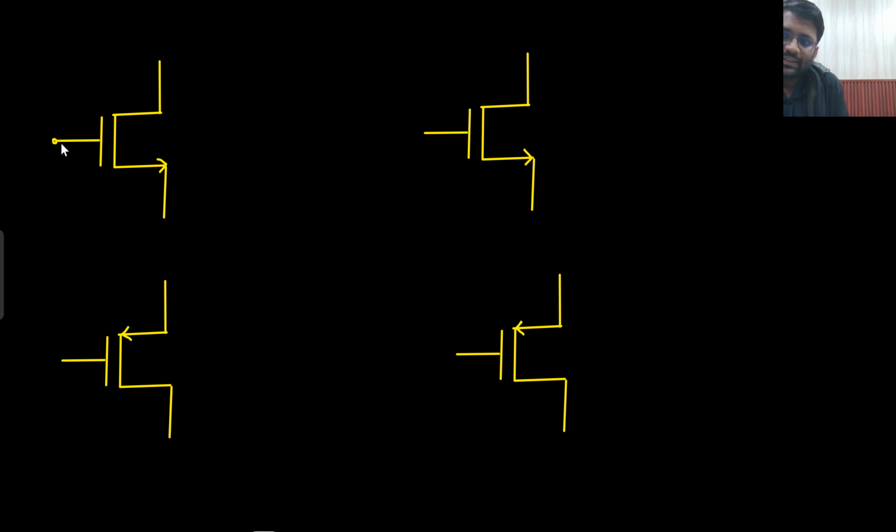Okay, now let's just say I say this potential is V1 and this potential is V2. Now in the MOS circuitry, this current I need to write down in the downward direction. So what will be the value of this current? It would be Gm into V1 minus V2, the current going from upward to downward. Whatever current is flowing here, the same current would be flowing here as well, so this current would also be Gm into V1 minus V2. In the MOS, the gate current would be 0 ampere.